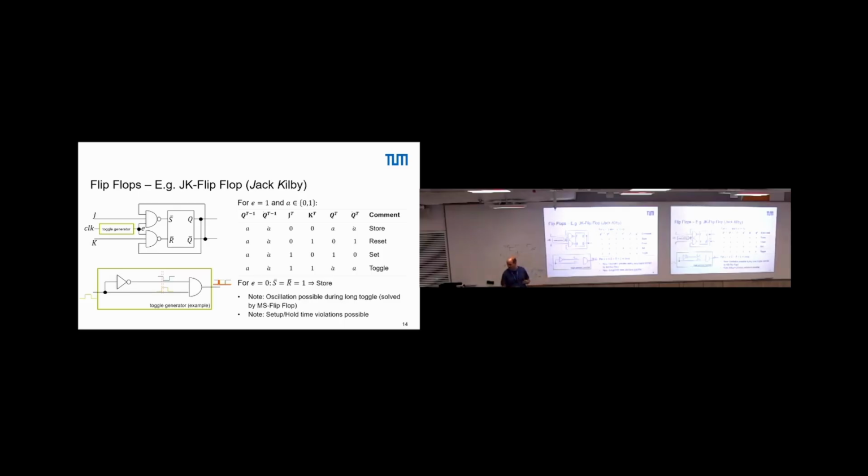Then we have at the input each 2 NAND gates with now 3 inputs, so another 4 plus 2 inverters. So we have a lot more gates, more area to implement such a flip-flop, also in more efficient designs. That is, if we want to store a large amount of data, several hundred bits, then we go for SRAM. If we need only a few bits, then we go for these flip-flops.